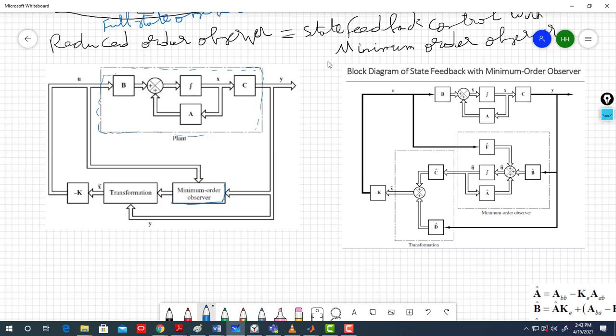So it has Y as input, it has U as input as well. So then, like the full order observer, what's the difference then? It has Y and U. Well, the output of it is not the observed state x tilde. It is actually a variable zeta.